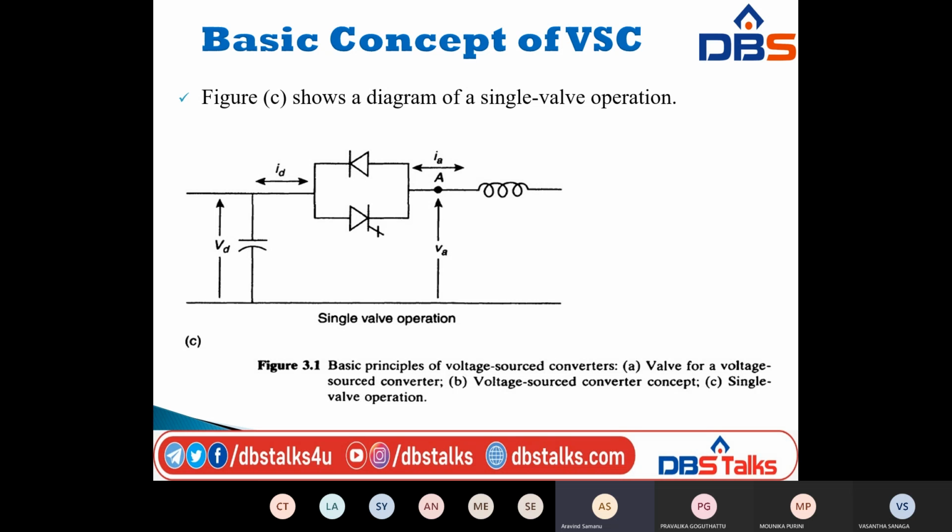This valve combination, that is a combination of thyristor and diode, has the capability to act as a rectifier or as an inverter, with instantaneous current flow in positive, that is AC to DC side, or negative direction respectively. This is basic to the voltage source converter concepts.